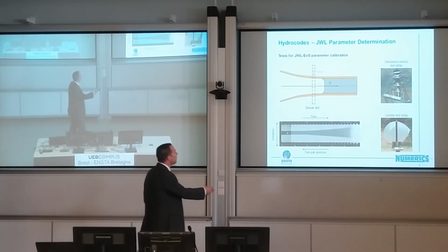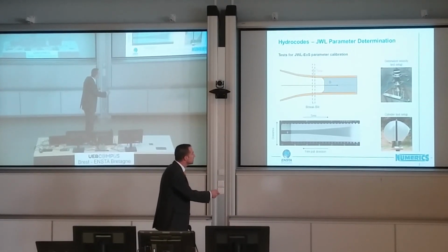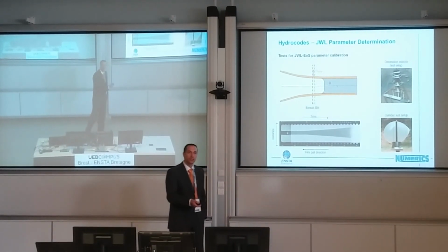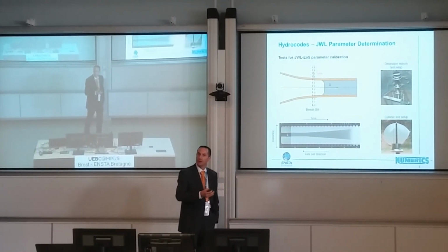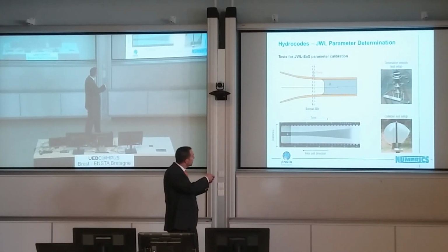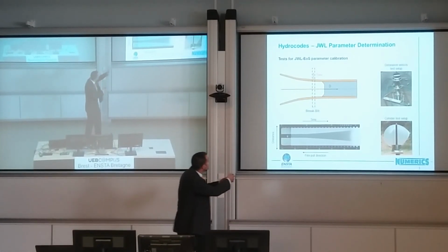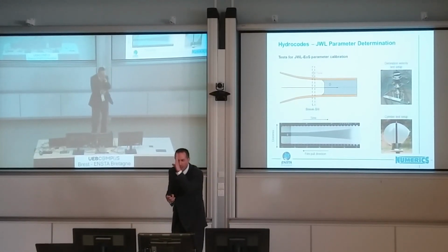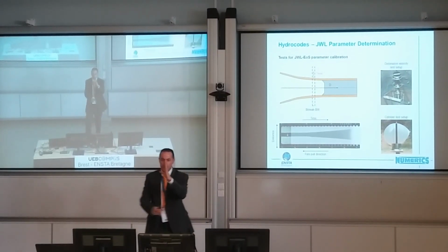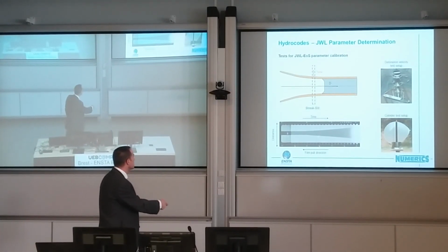So here's a typical cylinder test setup. The balloon here, that's argon, it's an argon flash to deliver the backlight during the test. And what we actually do is we use a streak camera which looks through this slit here and nothing else, just through the slit. And the film is pulled and we come up with something like this.